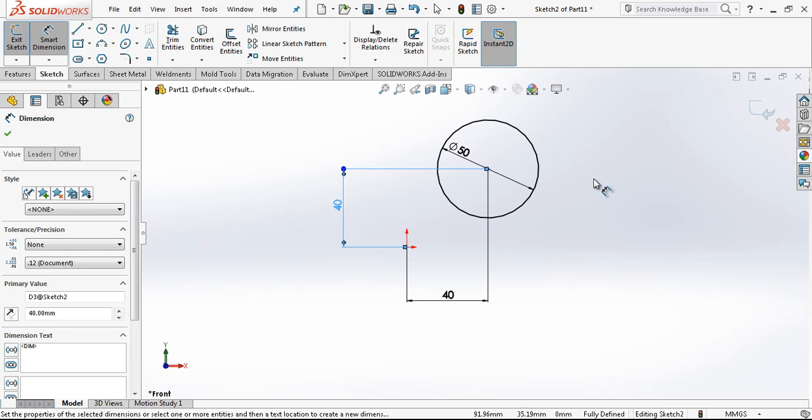That's why it's important. When we are drawing our models, there comes a time that you want to change the dimensions or make revisions. If you are not giving full constraints on your sketches, on your diameters, lines and whatever in the sketch, when you change the main dimensions of your model, everything is going to stay like the earlier stage.